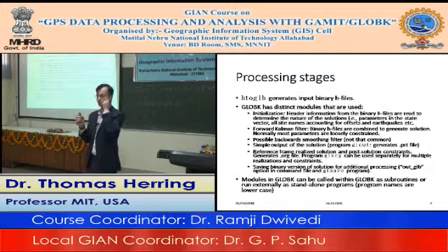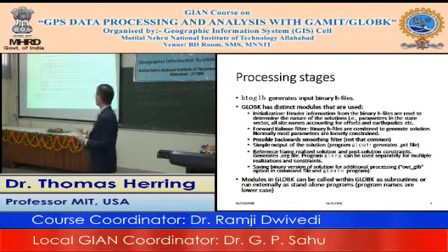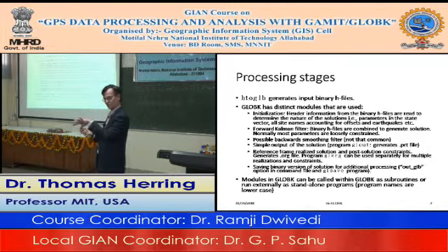It then also propagates that through the covariance matrix to get you the covariance matrix in that realized reference frame. So in the print file, typically the uncertainties of the station coordinates are several meters. In the GLOG file, after reference frame realization, they're generally down at millimeters and better. And that's done through this rotation, etc.